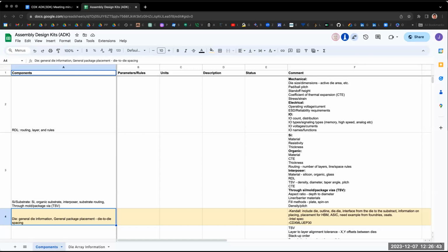There are other rules that you want to define, for placing things like capacitors, or you may need a rule on how far the die edge needs to be from the package cavity. All those kinds of things. We want to make sure the format has that, and we need a structure so the schema can organize these in a manner where it's easier to enter the information, rather than just having everything jumbled into one big file.